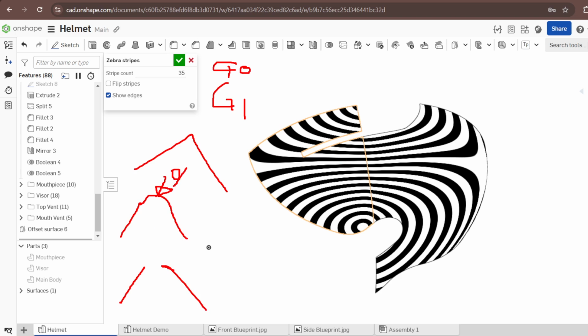This surface starts to connect, and these two tend to connect to each other. Each will have a certain radius. With G2 continuity, called continuous curvature, the rate of change of this one and the rate of change of that one are the same.